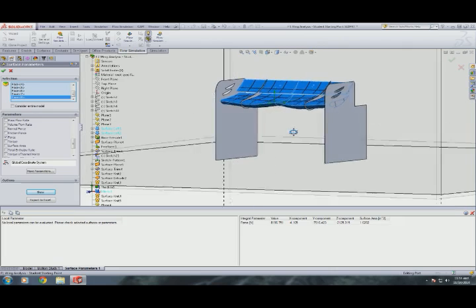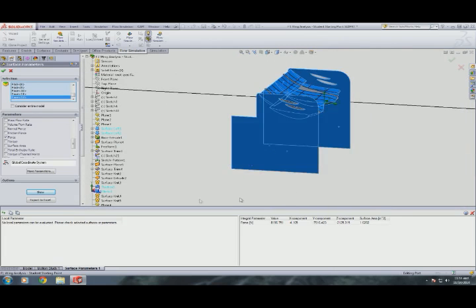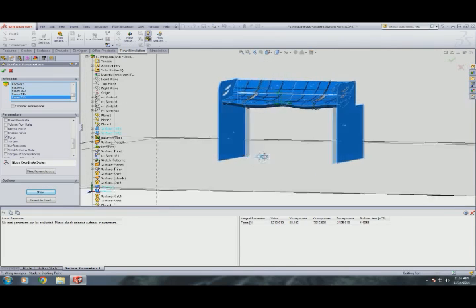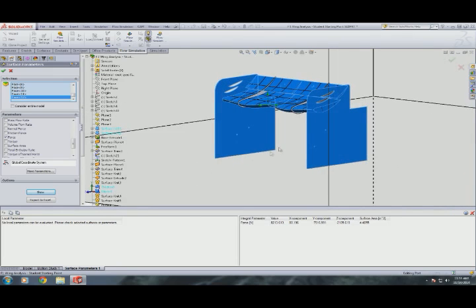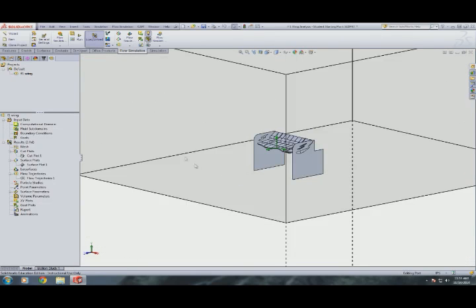You could go around, just continue adding these surfaces and click show again. It recalculates things, and the result changed by extraordinarily small amounts. So what do you know, the wing is the most effective thing at making downforce, lo and behold. But anyway, the thing we're more concerned with now is how to transfer these loads to finite element analysis.